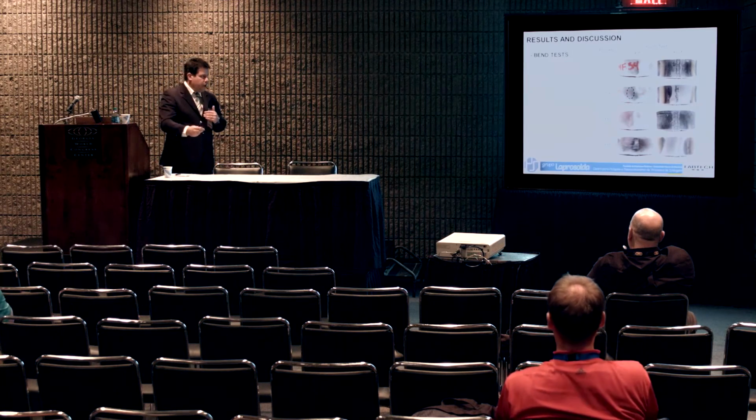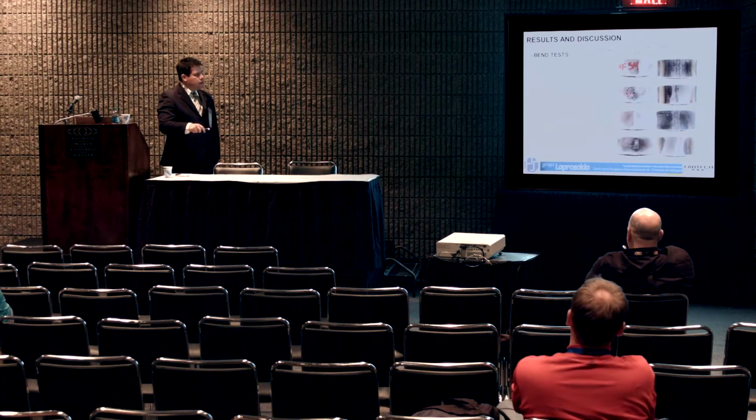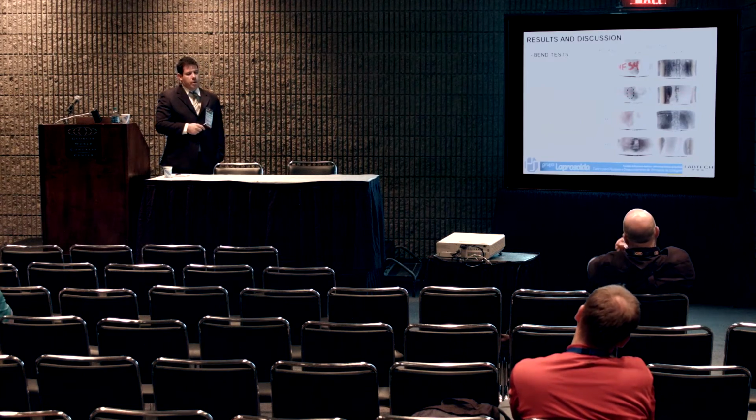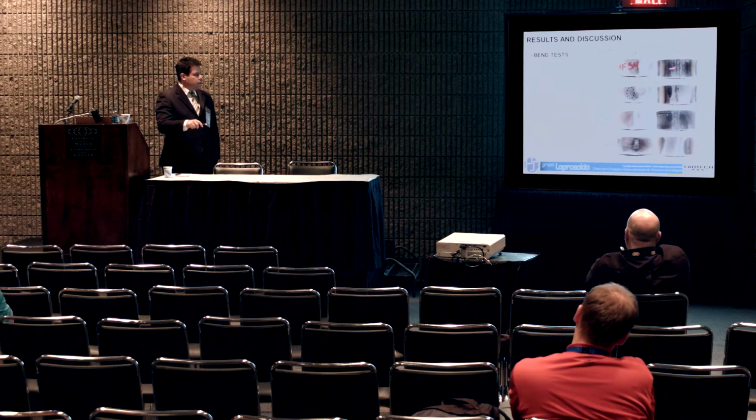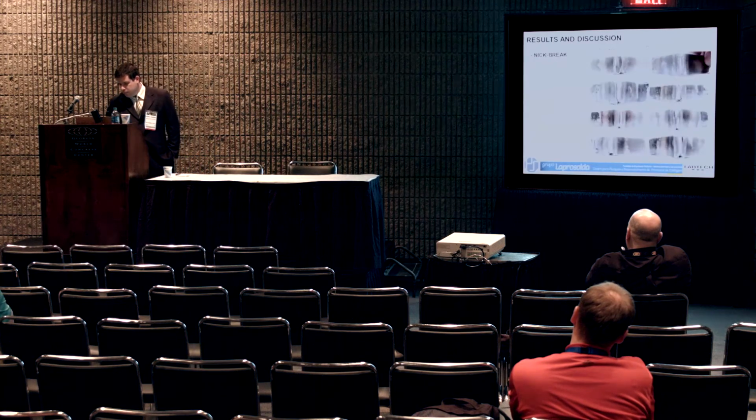But once you correct that lack of fusion, you don't have any problems in your bend testing. So up to now, all those three processes are approved, but the conventional one, no. We got some problems in the macros, and here again we got some problems in the bending tests. That's why I like bend testing so much.